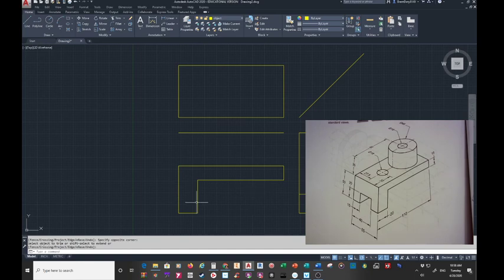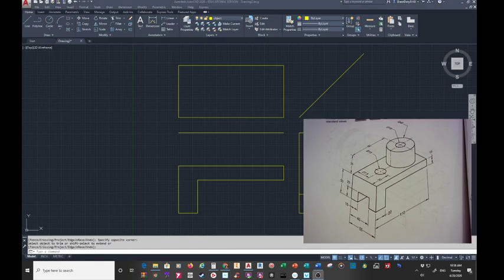Well, one thing I can do is project this line up here as a hidden line. And you're like, why is it hidden? Well, because if I look down from the top, if you look at your example, which, like I said, I don't know if the mouse shows up or not, the top there where it says 27.5 and 35, you're going to have a hidden line running up through there. If you were to think about it, yes, there's a line underneath there.